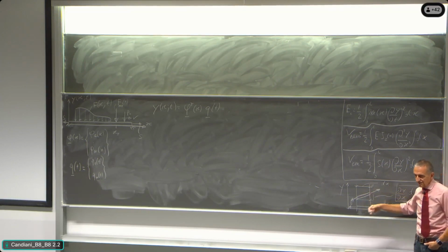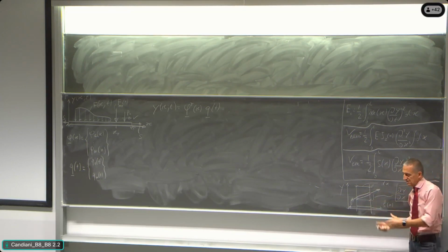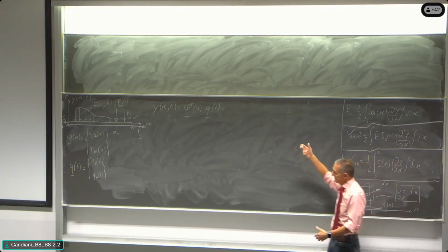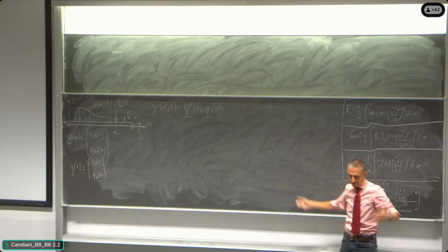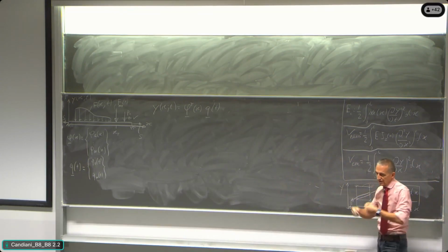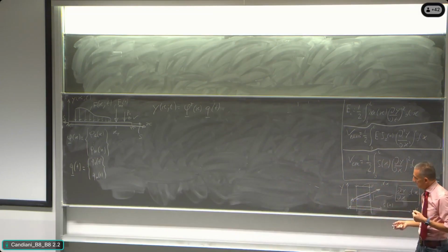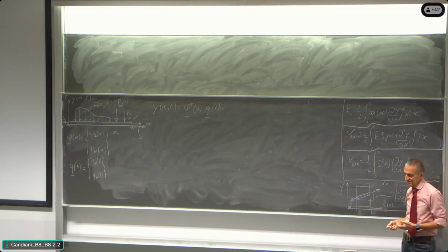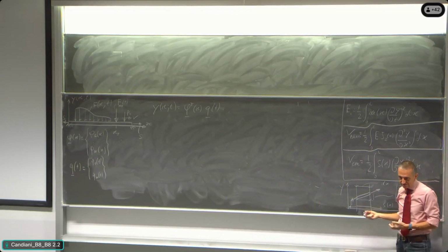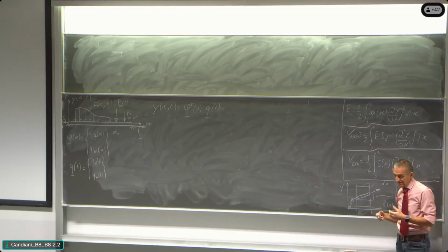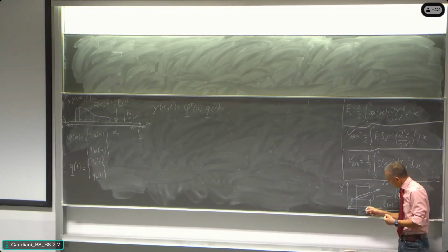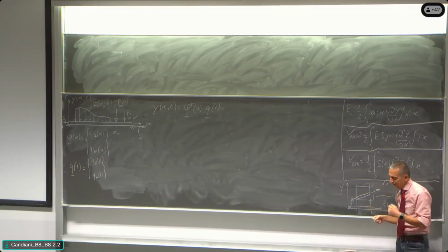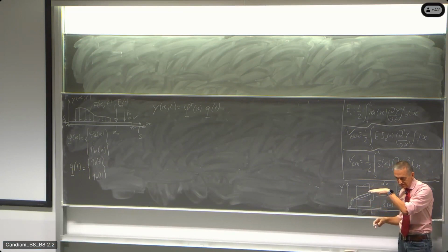But in order to say that, we are saying that when the cable is vibrating and has a shape that is not rectilinear, it has more energy in terms of potential energy, but it is longer. And if it is longer, we are saying that the tension is not constant here. It has been elongated, and so the tension is different, it is moving away from the value that it has when it is in a straight line, all right?